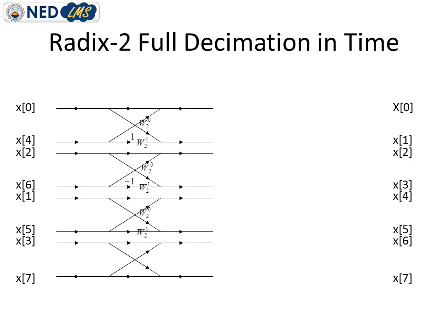Now how will you calculate A0? You will see that A0 is the combination of x of 0 plus the value coming from this arrow, which is x of 4, multiplied with W2^0. So A of 0 is actually x0 plus x4 multiplied by W2^0. I am again repeating, A of 0 is equal to x of 0 plus x of 4 multiplied with W2^0.